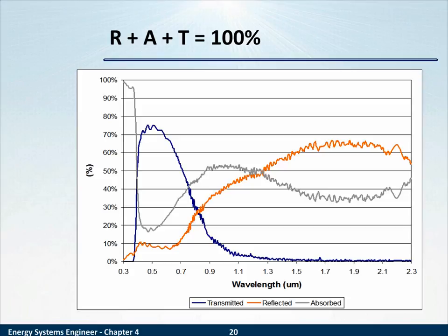outside it's 10 degrees Fahrenheit. The sun comes up, heats up the top of the window, the bottom's in the shade. You can have an uneven distribution of heat. Now understand, glass doesn't break because it got too hot. It was made at over 1,000 degrees. It breaks because it's unevenly hot.